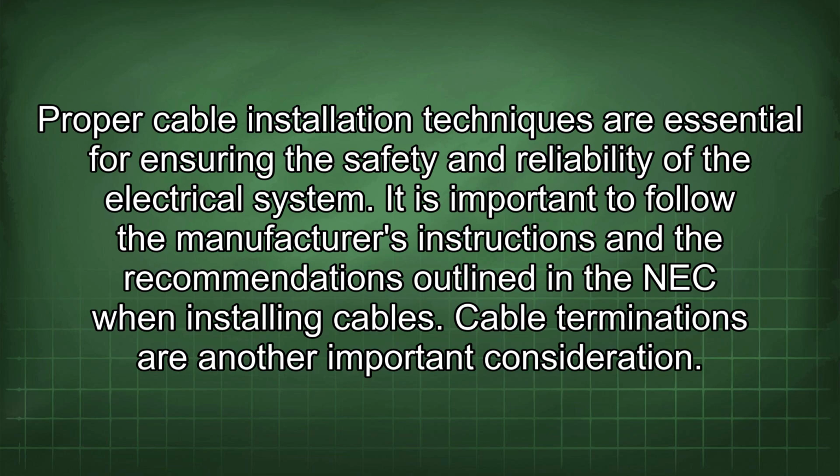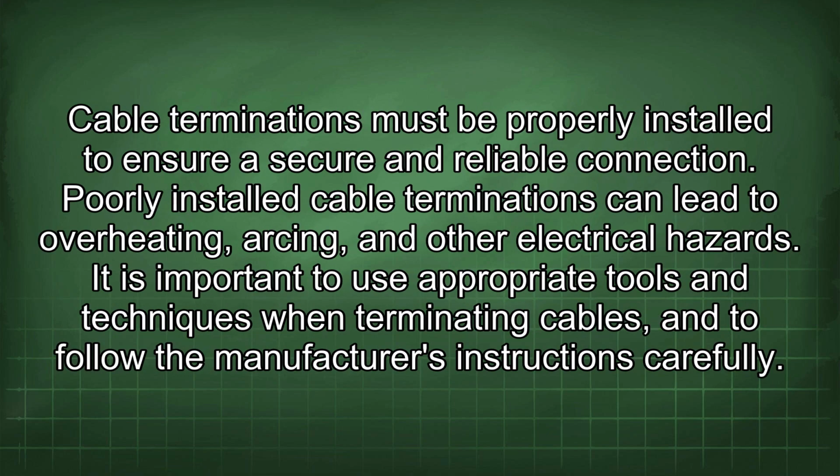Cable terminations are another important consideration. Cable terminations must be properly installed to ensure a secure and reliable connection. Poorly installed cable terminations can lead to overheating, arcing, and other electrical hazards. It is important to use appropriate tools and techniques when terminating cables and to follow the manufacturer's instructions carefully.